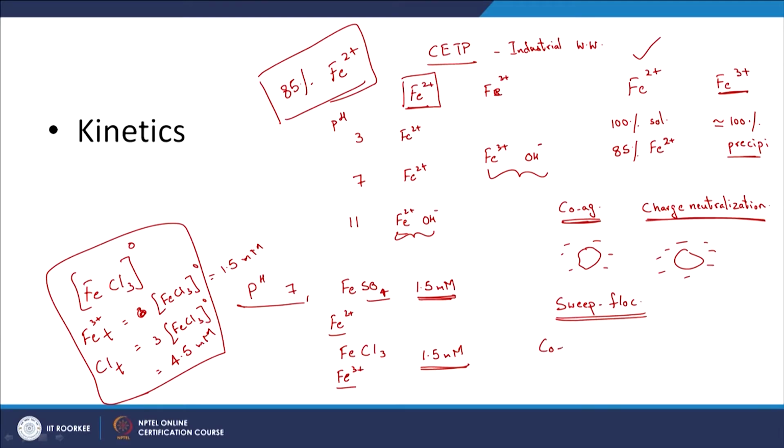That is one particular case. But more importantly though, we have co-precipitation. So, people mistakenly call this coagulation, but this is not coagulation. This is the principle involved, it is co-precipitation. Why are we calling it co-precipitation? As in when you add Fe3+, you see that it can precipitate out in the form of Fe(OH)3, almost all of it. So, these sites of solid Fe(OH)3 act as sites for adsorption, for the other suspended particles to be formed or agglomerate on this solid.